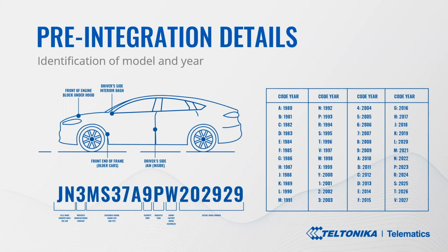Basically, according to the symbol provided in the 10th place, you can determine the make year, but please take into consideration that there are repeated characters in the table, and to fully confirm the make year, you have to make sure to follow position 7 of the VIN number.